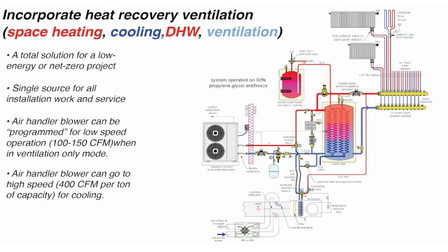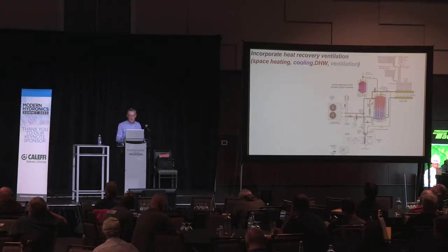Set up a manifold. Half-inch PEX is typical, or PEX-aluminum-PEX, or PERT. The tubing is all well within the temperature and pressure rating of what we need. You could go out to panel rads, towel warmers, radiant wall panels, floor heating, okay? And it's all fine as long as you design all those heat emitters around the same water temperature. I can't run a panel radiator at 120 here and run a floor circuit at 105 over here without putting mixing valves in, and that would complicate the home run system.